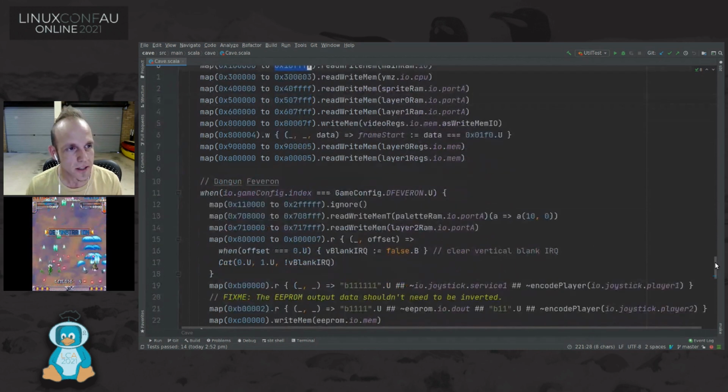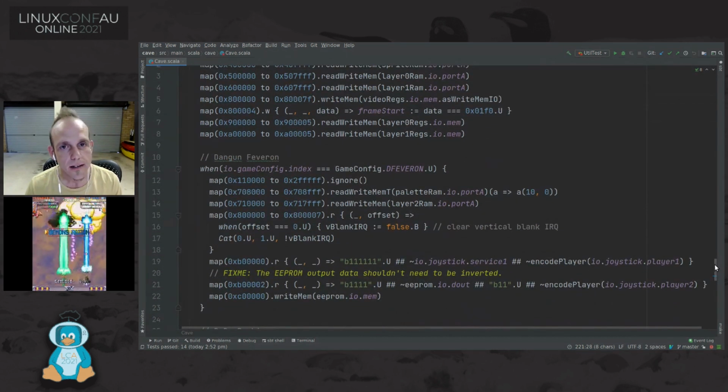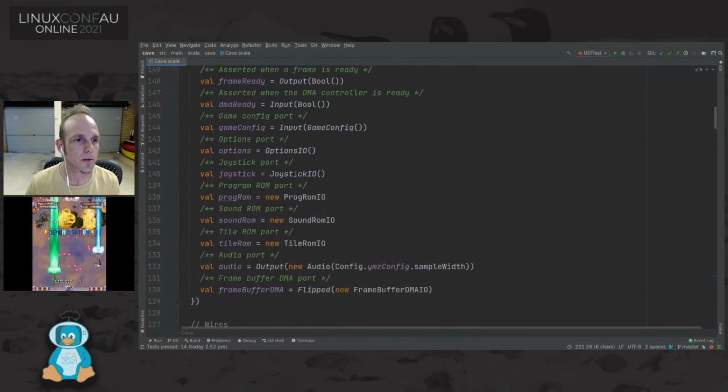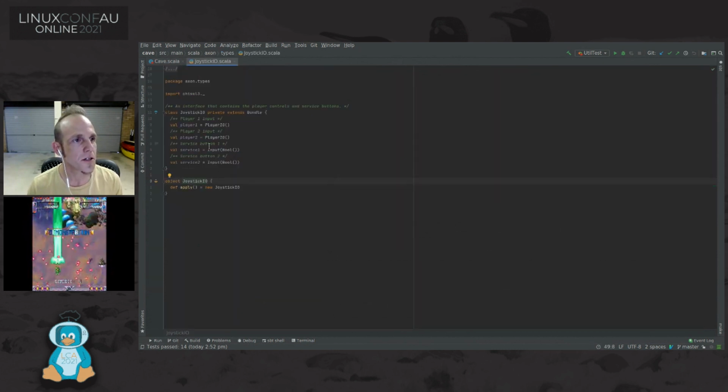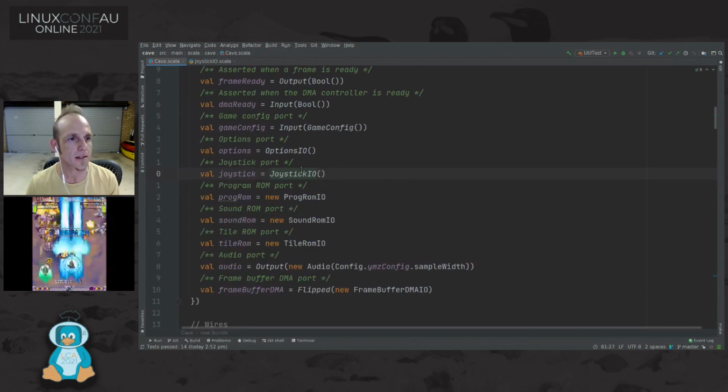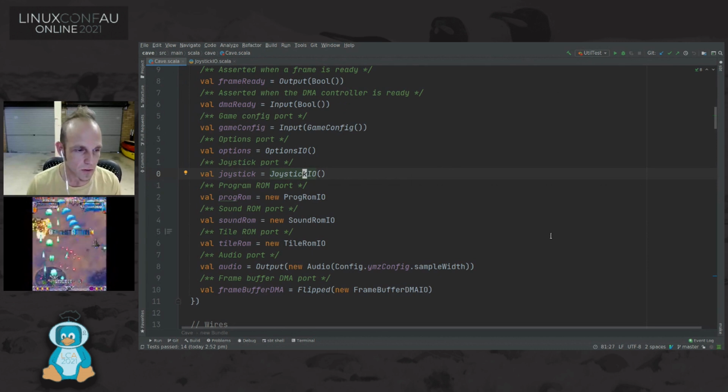That's quite nice. I really enjoyed that about Chisel. And then the other thing I mentioned was being able to use bundles to pass around all these signals together is a huge win. So not having to pass all these individual signals around, I can just pass them as a bundle. Fantastic. It lets me move so much faster and makes the code so much more readable.